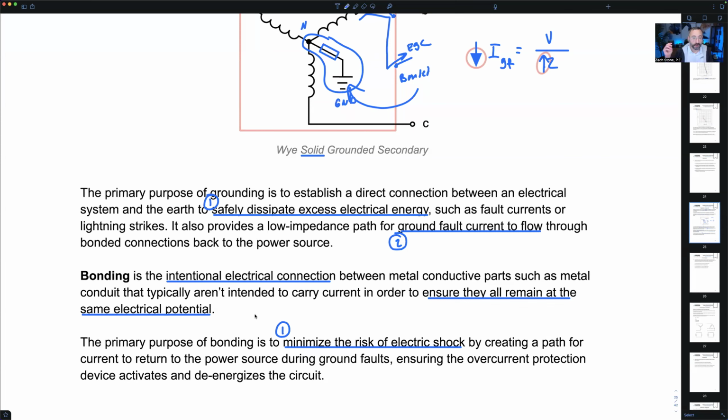A conductor by itself carrying power is doing that all the time, but it's typically minor enough that it doesn't cause any problems. Well, if I have really sensitive electronics and instrumentation, then that little bit of interference can create inaccurate measurements. And now I'm steering my submarine all backwards. So we also want to bond everything to help eliminate that. Think of it like static electricity almost.